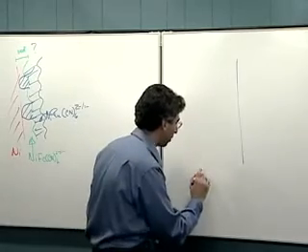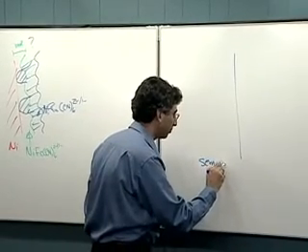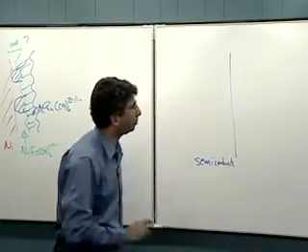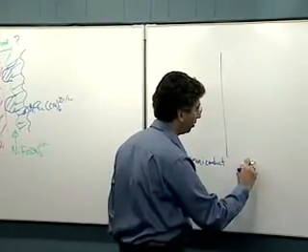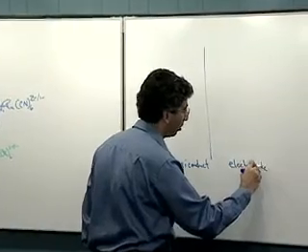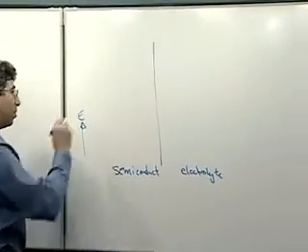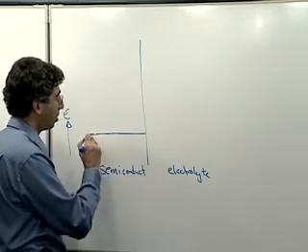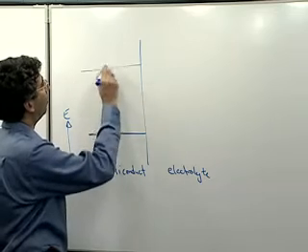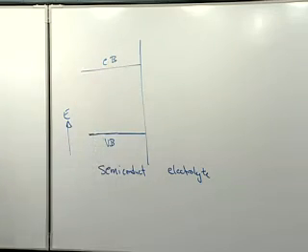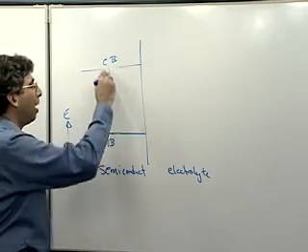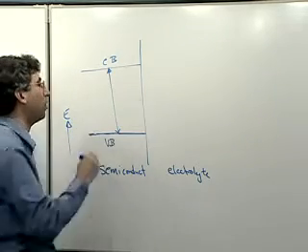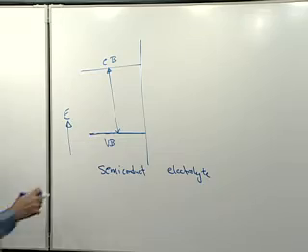So here's a semiconductor. And here's its surface, and out here is an electrolyte. And on this scheme, we have energy, and it's going in that direction. A semiconductor consists of a band structure, and so we have a low energy band, which is called the valence band, and a high energy band, which is called the conduction band. There could be a whole bunch of these, but let's assume there's just one valence band and one conduction band. And we have a region in energy in between those two where we have no allowed states, called the band gap.